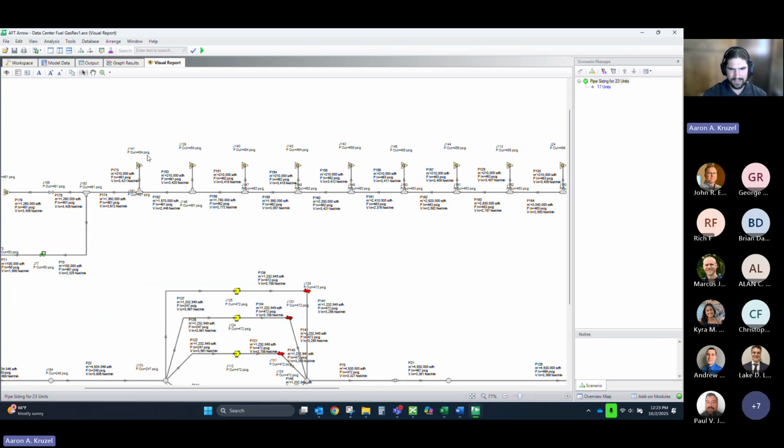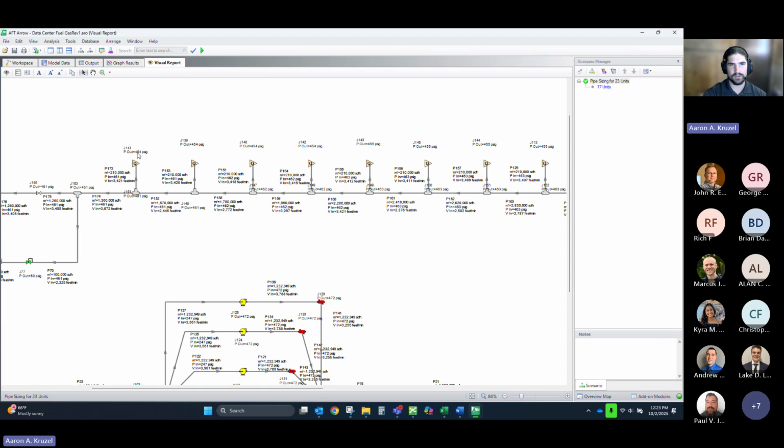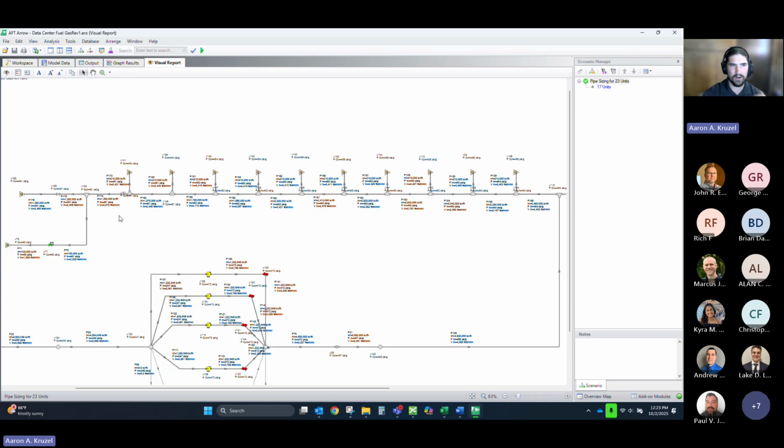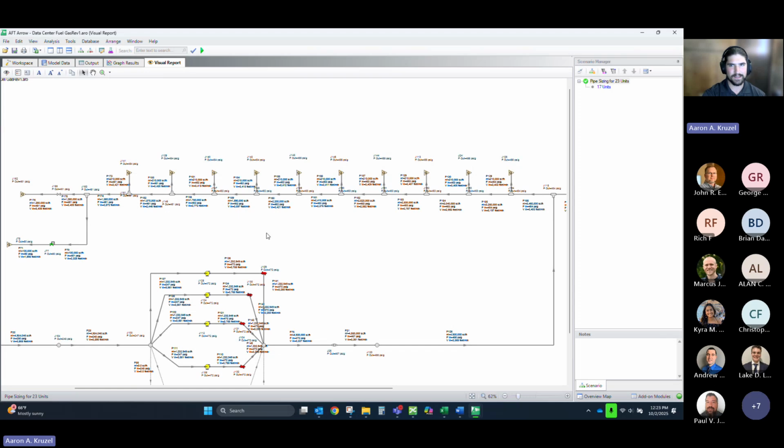And in addition to what we're seeing with the last one, the velocity, we can also account for pressure loss. So accounting for how much is actually dropping in the system, lost to the pipe. And we can make sure that all end users are going to get a consistent or at least high enough pressure at the end result. So that's the twofold piece of how we design our systems: both having the velocity to meet the sound requirements as well as the degradation of the pipe, but then the pressure drop to make sure that the end user is actually getting what they need.